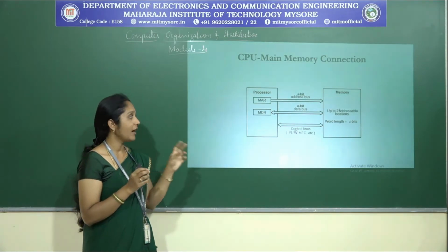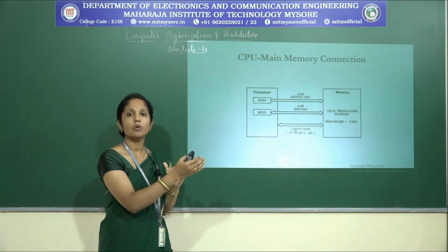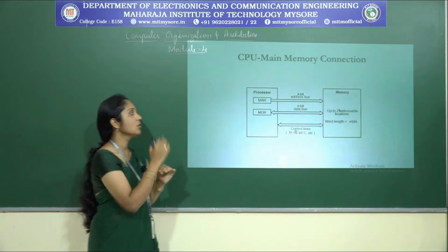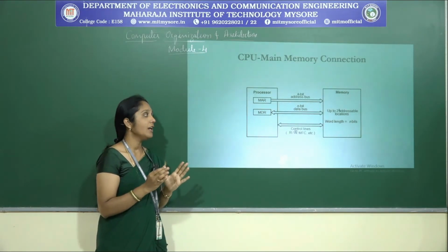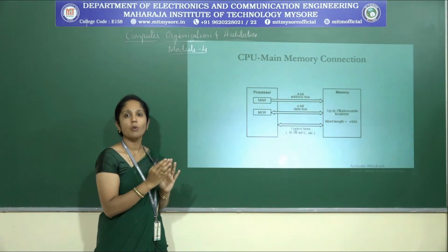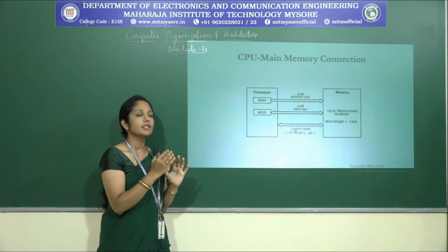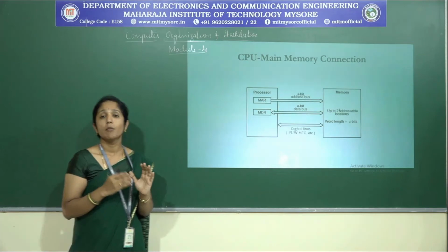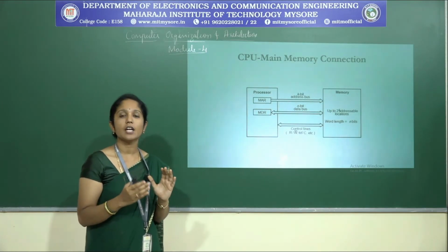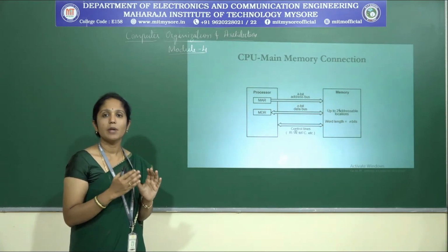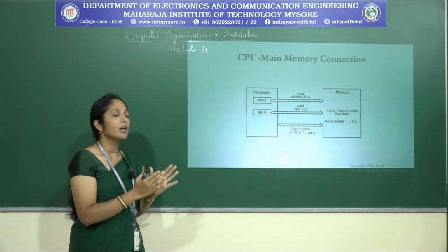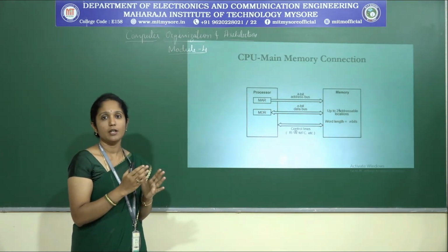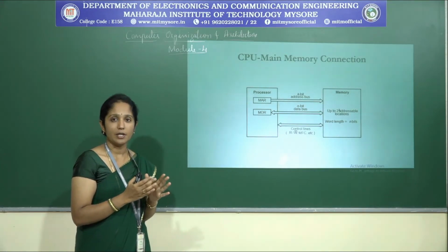So depending on the address, the data will be read from the memory and placed over the MDR. Once the fetching action is over, the MFC, memory function complete, signal will be made high, which indicates to the processor that the function, the read operation, is completed.